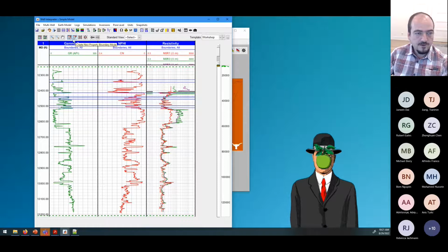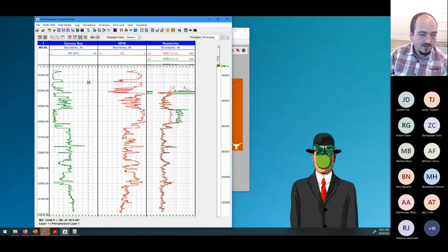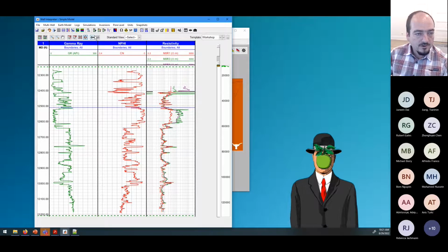That's okay. Like I said, you can modify these too, but my advice, just work with petrophysical. You can also delete them. If you click on this X, you can just X them out. You can also click, drag and drop and delete everything in that interval. You can also move them, and this is actually a little more useful. You can move them up or down. When you're refining your Earth model, you may want to make these kinds of movements. Just click and move to whatever you think is a better position. And the last two icons, the arrows back and forth, are just undo and redo.